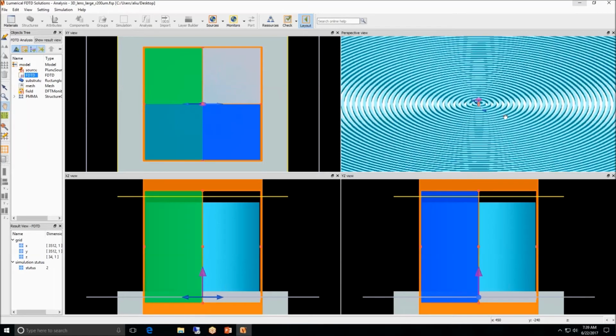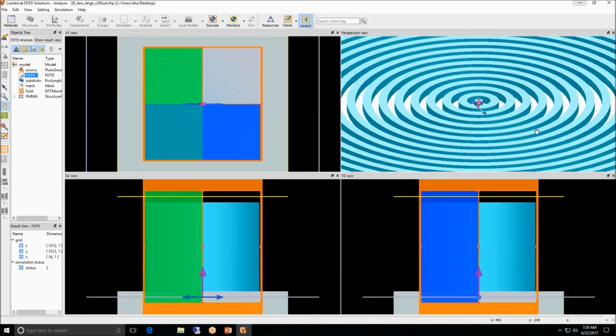And for example, if you zoom in, you can see the grooves for the different gratings. So for a lens of a radius 200 microns, my total simulation region size was about 420 by 420 by 2 microns. And this simulation takes about an hour to mesh in FDTD and about an hour to run on my desktop. So even these reasonably large size lenses can be simulated in a reasonable amount of time in 3D. And once this is done, I can take the same monitor.